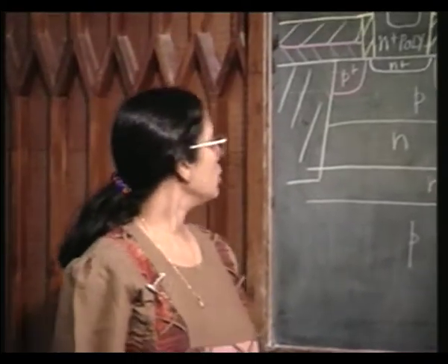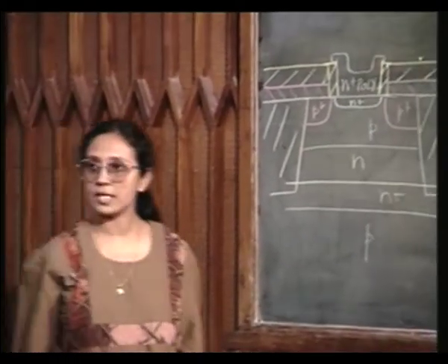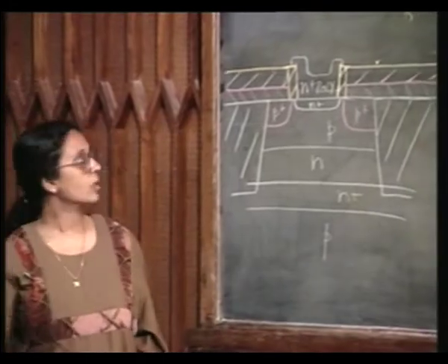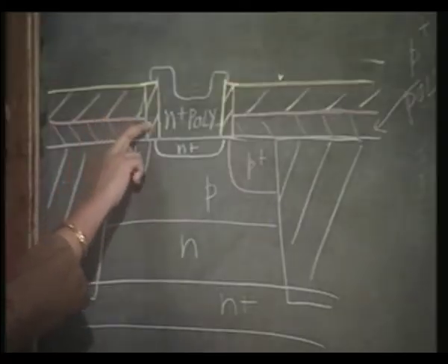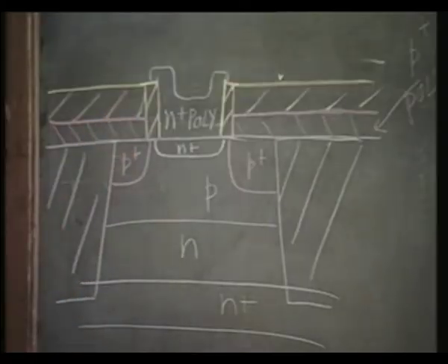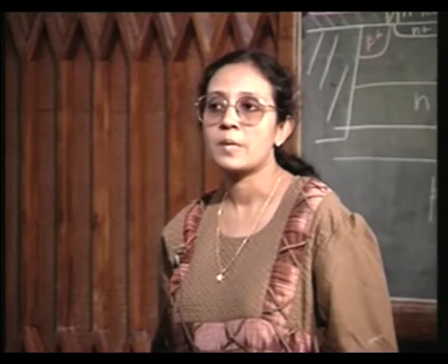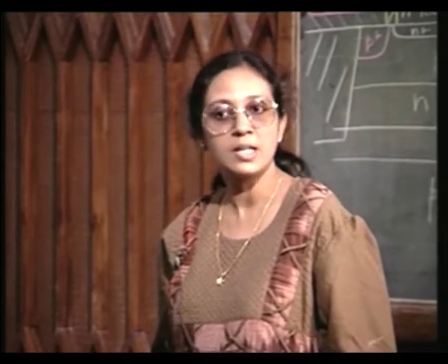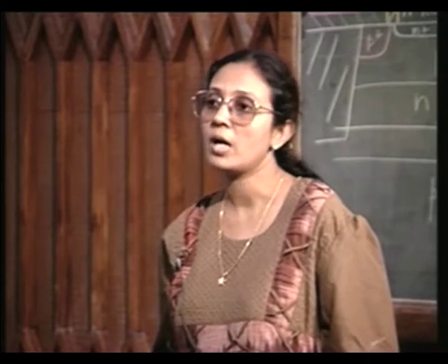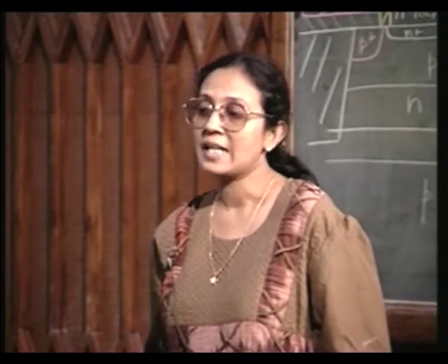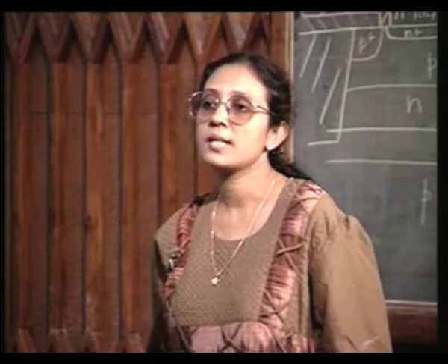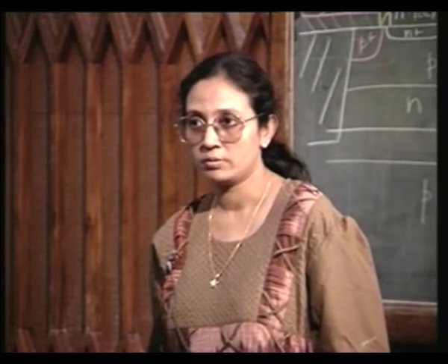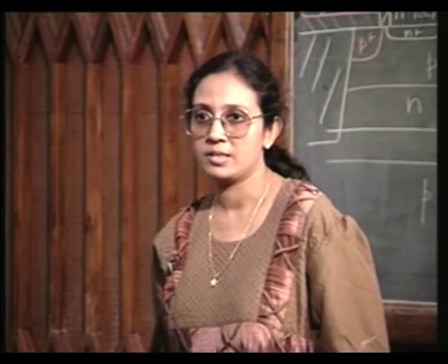So, you can also have a variation of the same theme, you know. What you could do is, in this case we had deposited CVD silicon dioxide. Instead of that, you could have an undoped poly layer deposited, so that your spacer is not made of CVD SiO2, but it is made of undoped poly. And later on, you could oxidize this undoped poly. What are the advantages?